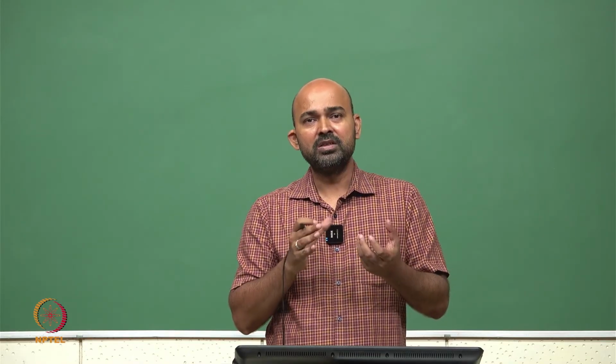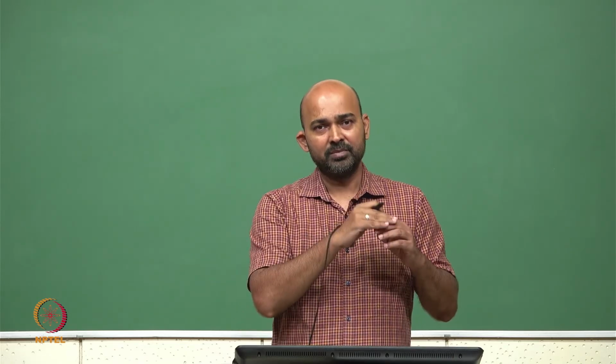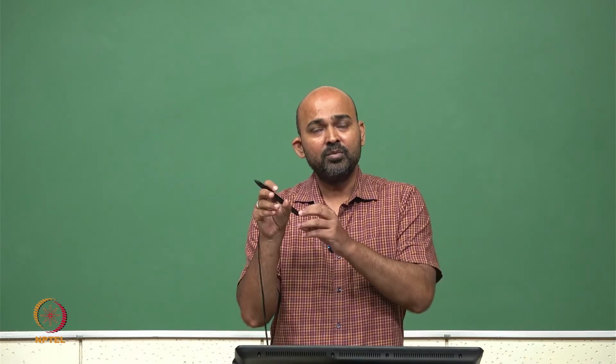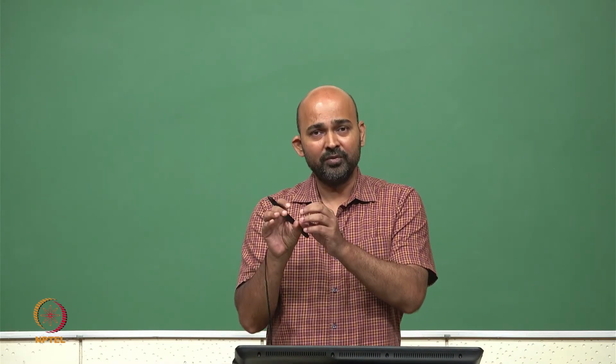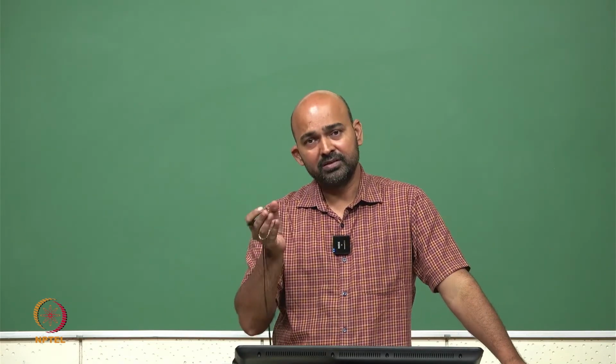dangerous for circuit reliability, because when we design all of our circuits, we assume that 5 volt is the maximum voltage which will happen, and all the circuit is safe up to 5 volt only. If there is a very high overshoot, for example it goes to 6 volt or even 7 volt, then our other circuits which are seeing this voltage, or if this voltage goes to the gate of a MOSFET that is only tolerant to 5 volt, that MOSFET gate will be damaged.